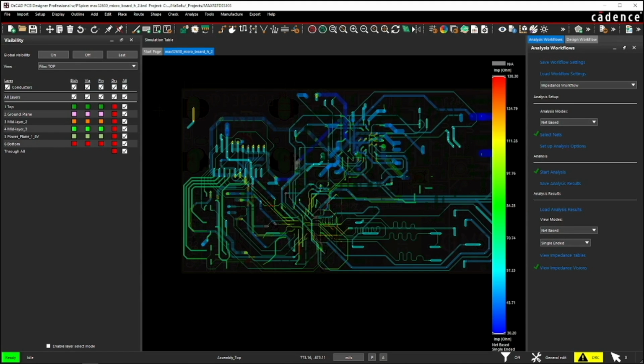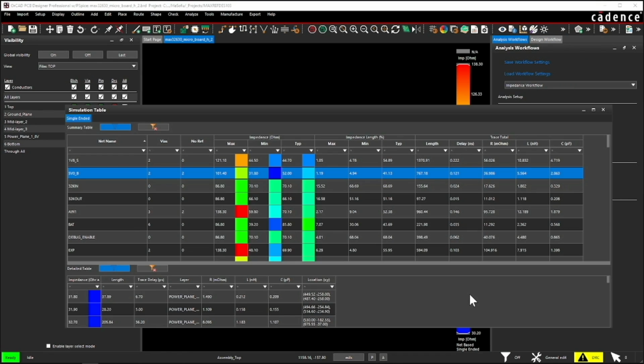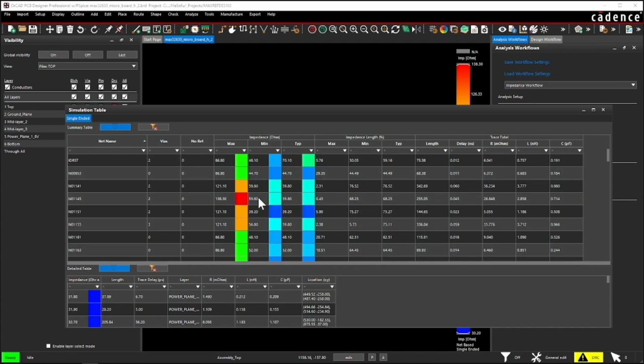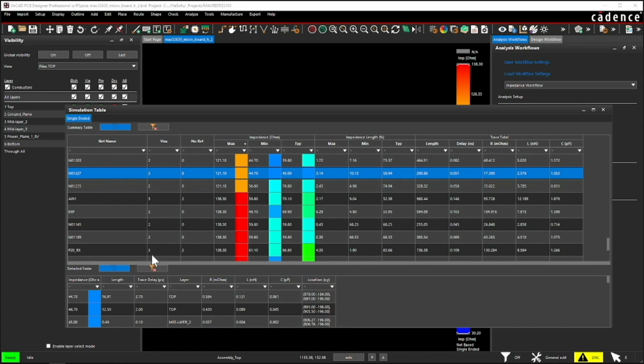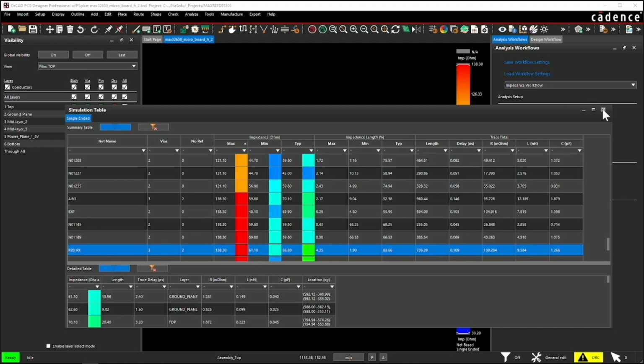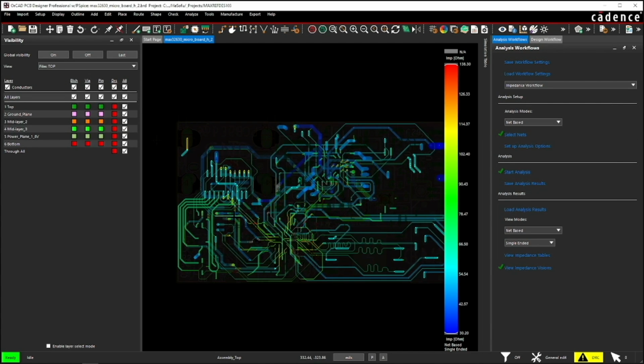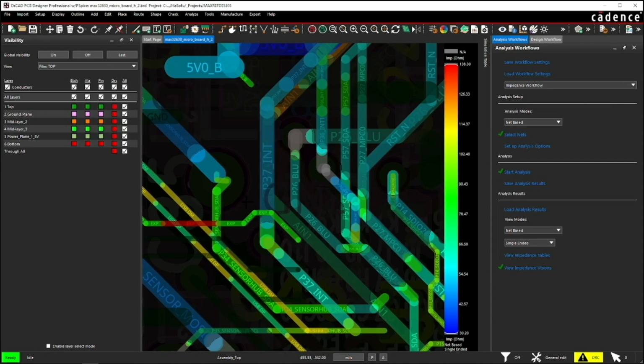The designer followed these principles, and now we see how the impedance profile turned out using impedance vision. Absolutely wonderful. The signals have been accommodated and the overall voltage and impedance profiles look great. And we see that in the impedance table as well, showing us that there are very few red spots, that is, high impedance areas. And this is great if you really want to get into more detail with precise numbers, and if you want to sort them. So you'll see that only some of the traces have a high impedance, and those are namely the ones that go over gaps in the PCB layout.